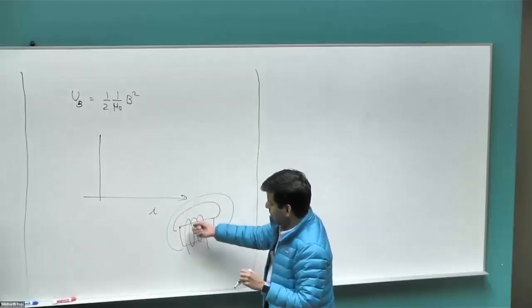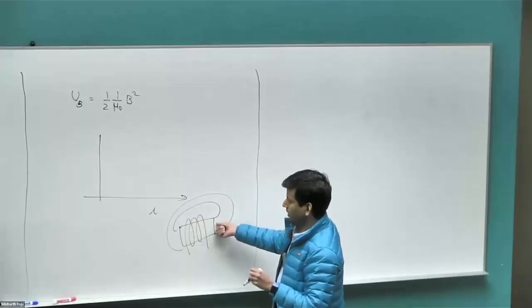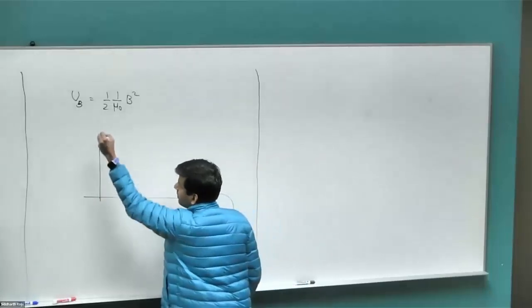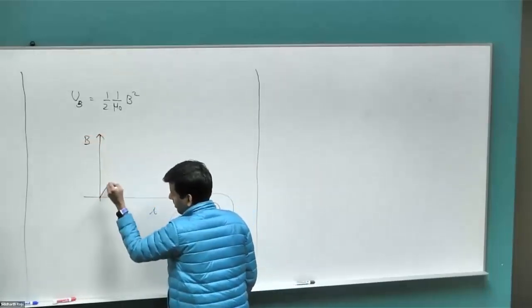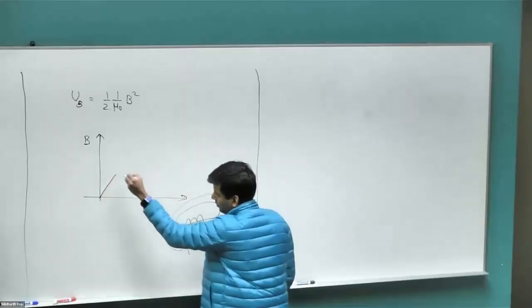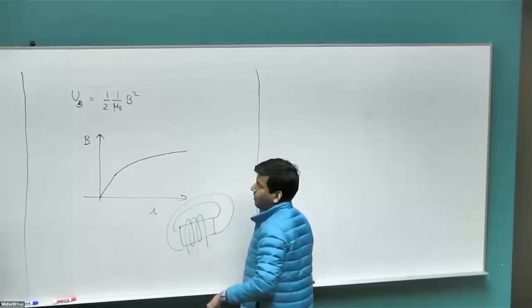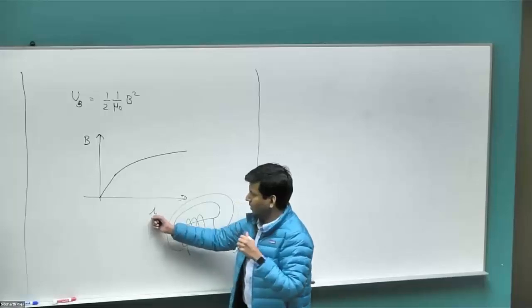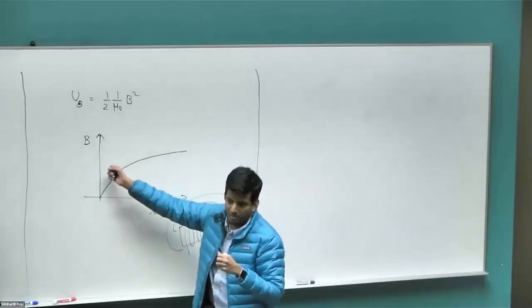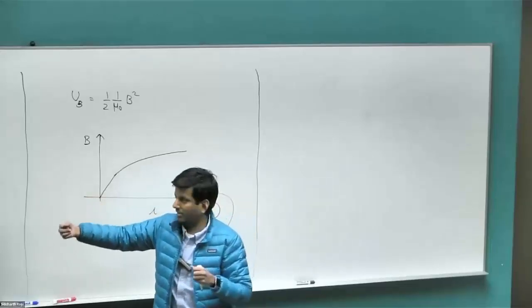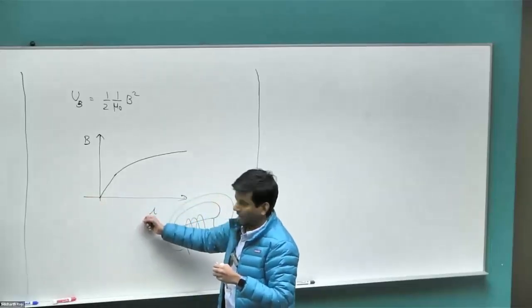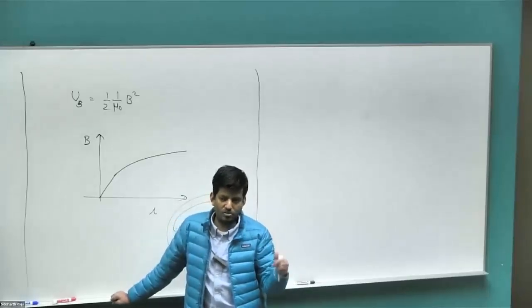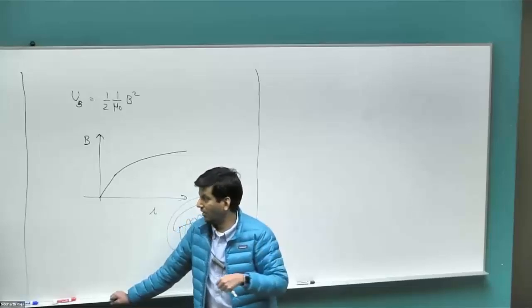And you start pushing in more and more current, and you have some kind of sensor, a Hall effect sensor or something, with which you measure the magnetic field that's being generated. Initially, it will appear as if it is linearly increasing, right? After some point, it will start to saturate. And once it saturates, it no longer makes sense to keep putting in more current, because you can double your current but you won't see double the increase in the B field. It becomes less and less rewarding to put in more current, because putting in higher currents is also a problem. First, how do you generate the larger current? And second, the higher the current, the higher the losses, because you have I squared R losses in the windings that are creating the magnetic field.